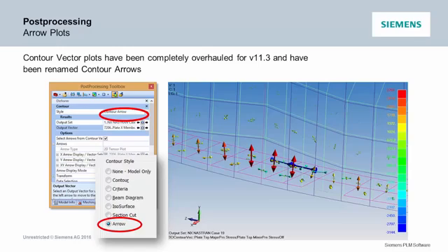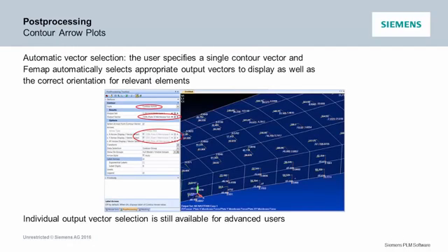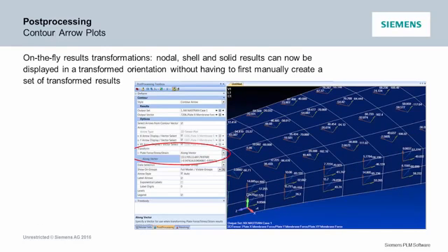And we set this up so that when you pick, like, membrane forces, when you pick X, Y, or shear, it automatically goes and gets the other components and plots them at one time. It just does it for you. You don't worry about it. If you then press the transform button, it just transforms them. You don't have to go set up a bunch of stuff. It's so easy now to make a force plot, transform it in any coordinate system, see it on screen. It changes the arrows to something that makes sense.